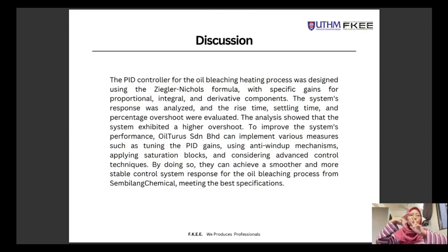We use the 20 milliampere input signal, so the discrete transfer function was used to determine the process gain K, time delay and time constant, and the Ziegler-Nichols formula was then applied to obtain the PID controller gains, where Kp was found as 2.23277, and Ki is 0.00223 over seconds, and Kd is 558.639 seconds. These gains were used in the design of the PID controller.